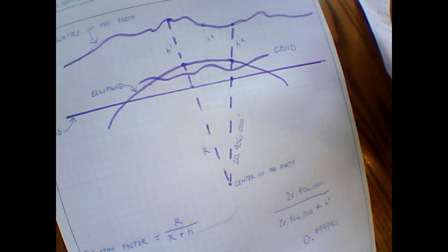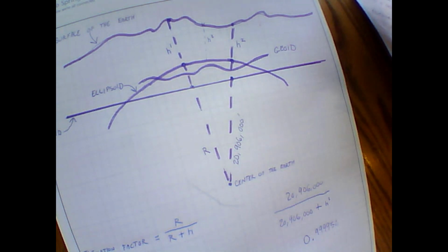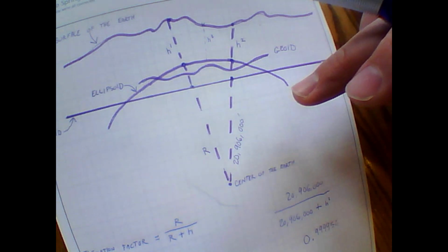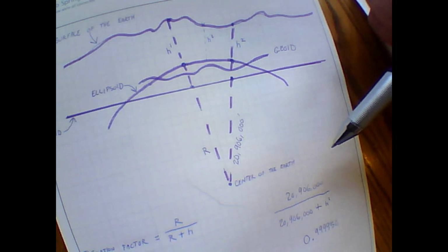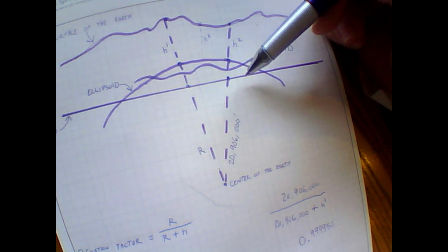The scale factor, the reason you can't find any information out there on what this thing is and how to calculate it is it's really complicated. I'm not even going to go into it. It's more so these things are published. Years ago, they had tables where if you were at this latitude, you would be this. It would know roughly where your ellipsoid height was and where that ellipsoid was in relation to the grid. So they used to have just charts where you'd say, okay, I'm here. This is approximately what it is, and this is why it's kind of just published information now.